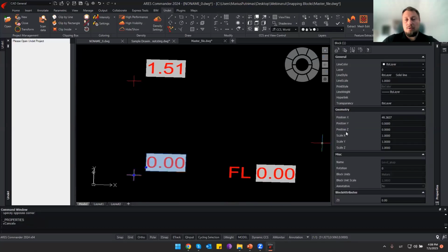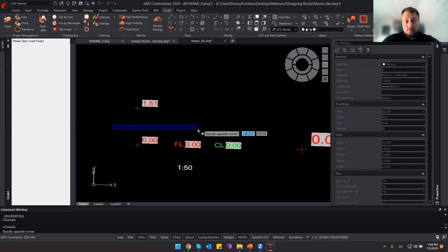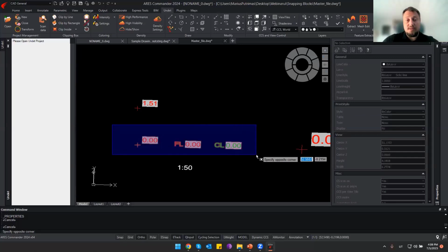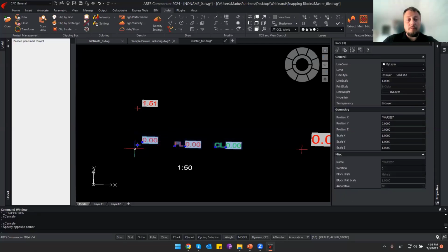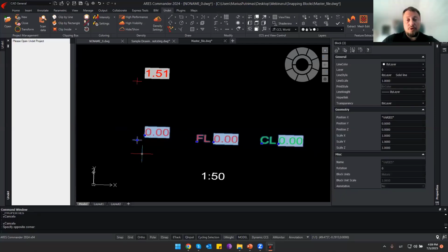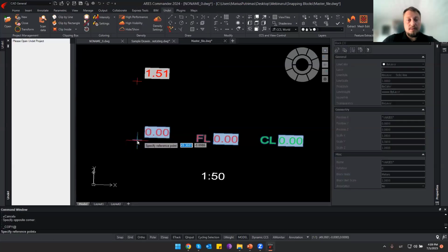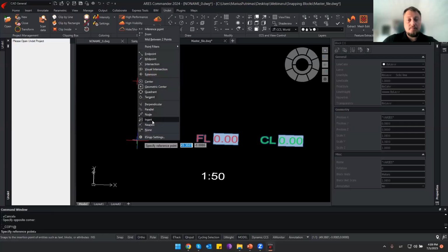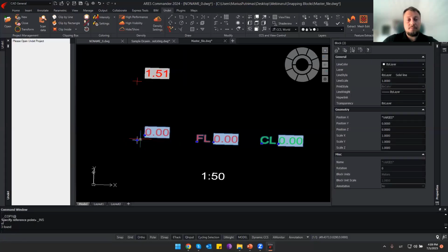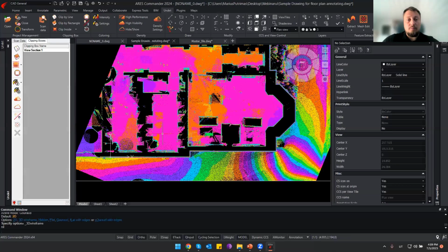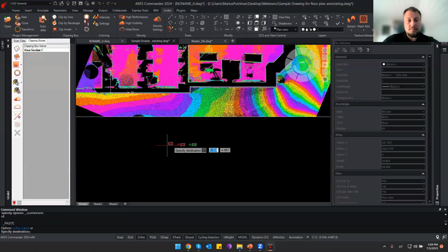If a block is on the position Z, it's showing with 0. And if you shift the blocks, it will show the exact Z position in the attributes of the blocks. So I will copy these blocks to my original file for floor plan vectorization. So pressing the right mouse button, copy the reference point, selecting the insert snapping mode, going again to my file, pasting these blocks over here.